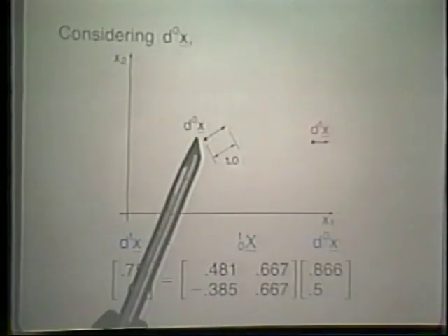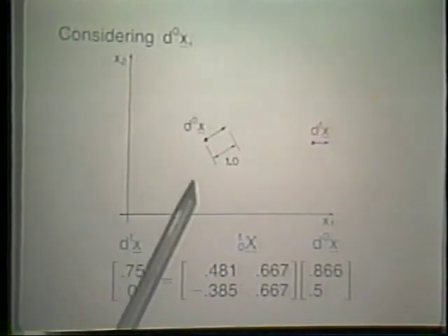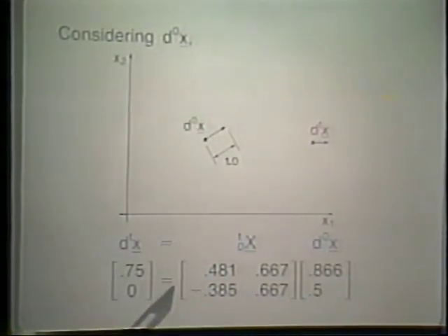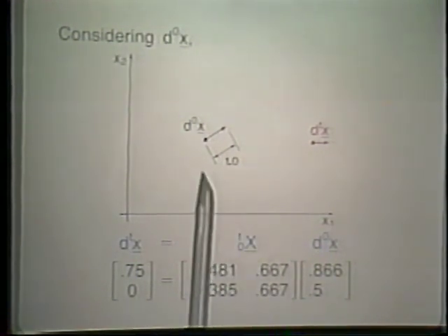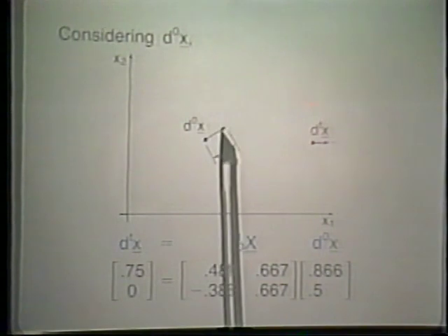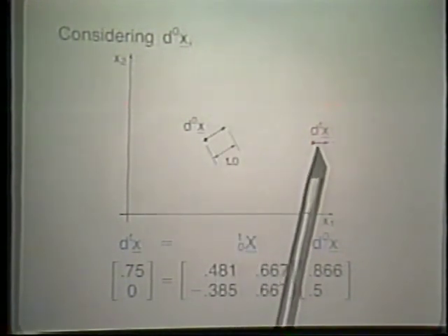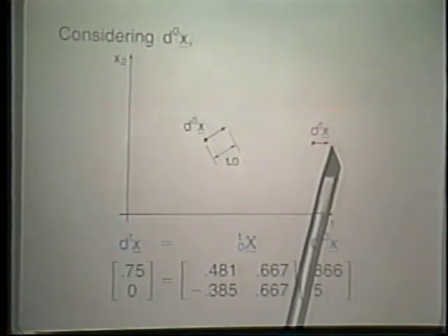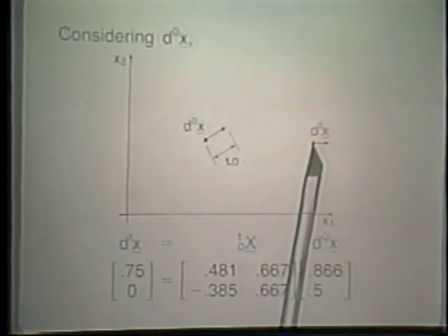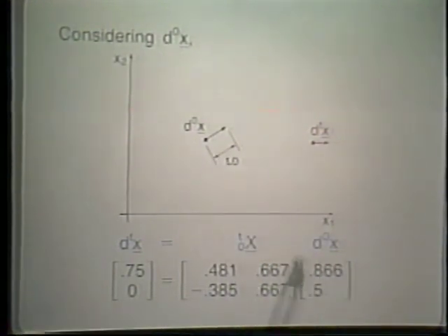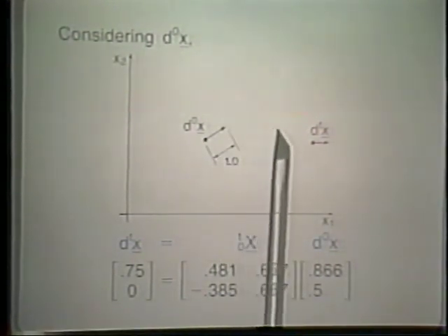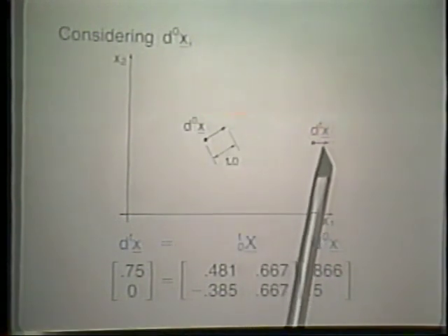how the original fibers, or the fibers in the original configuration, will rotate and stretch. And that relationship is given via the deformation gradient, as shown here quite physically, because this fiber originally here has rotated into a new position and has, in this particular case, been compressed. So this relationship tells us how the fiber has moved, rotated, and compressed.